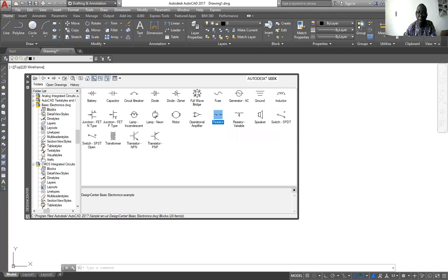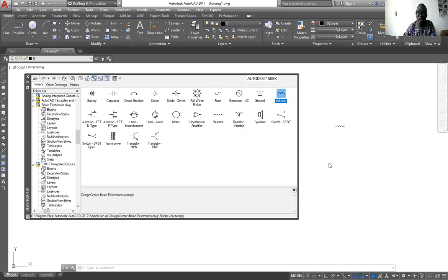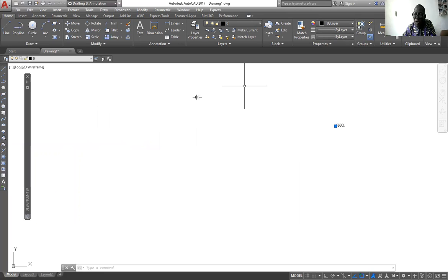Yeah, that's the resistor there. You can bring out your inductor. Where's the inductor? Okay, this is where you see the inductor here. You can drag it out here. Okay, they seem to be overlapping here. Let me move it to another place. Let me move this. I'm trying to move it out from the overlapping. Okay, that's your inductor there. Press escape to remove any.